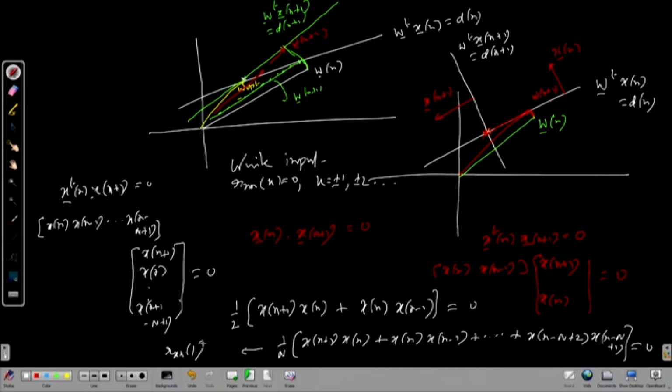But if there is any random process, we expect maximum correlation at the minimum gap. Their adjacent samples are highly correlated. If that is 0, further correlations at larger gaps will also be close to 0, which means for white input, in the absence of noise, NLMS will converge very fast, just 2 iterations.